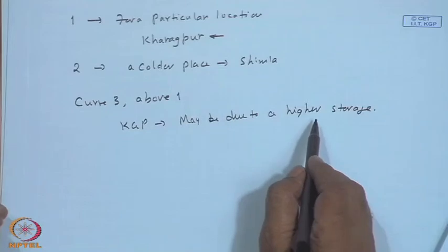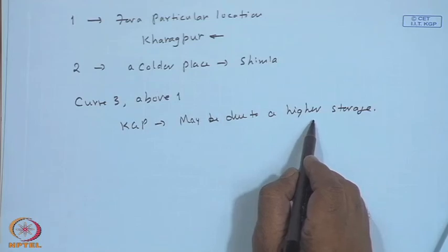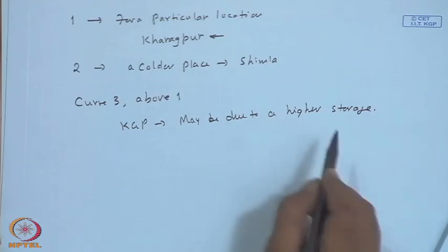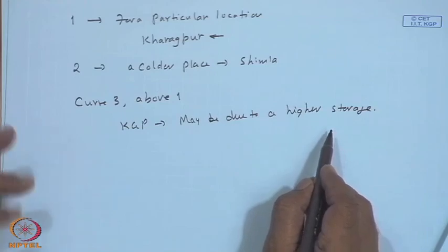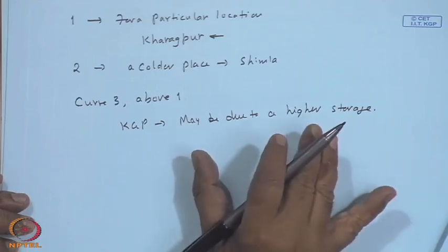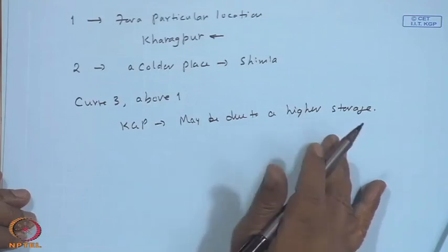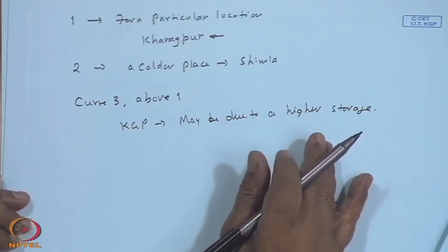So, in a month like June, if there is extra energy delivered, there is a large enough storage for that energy to be stored, and it can be utilized on a lean day when it rains or in a subsequent month like October, November, December. In principle, if you have a seasonal storage, the effectiveness will be very much improved, though one has to account for whether that large seasonal storage is cost effective or not.